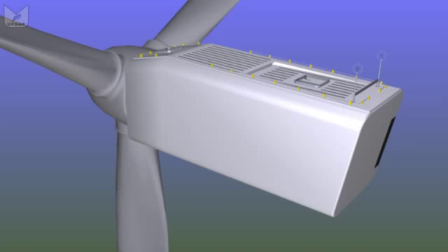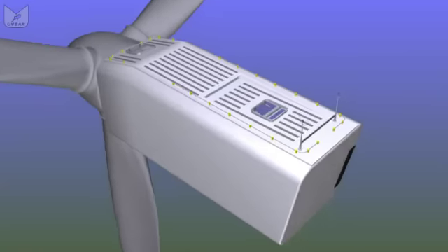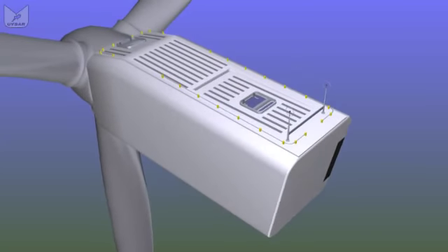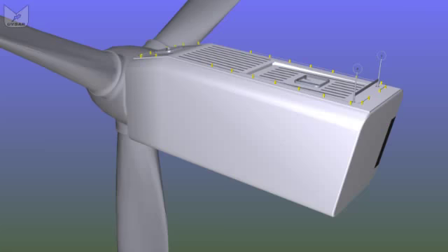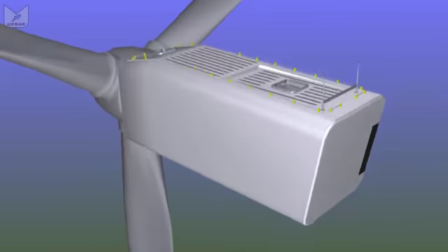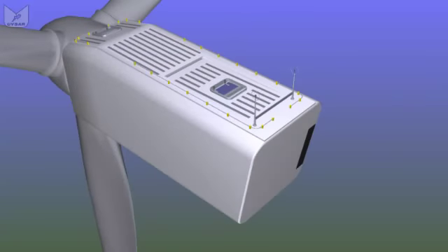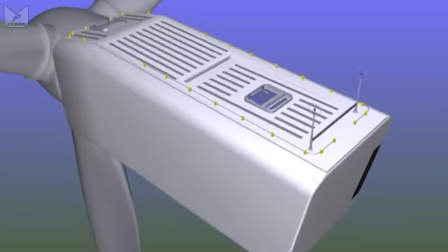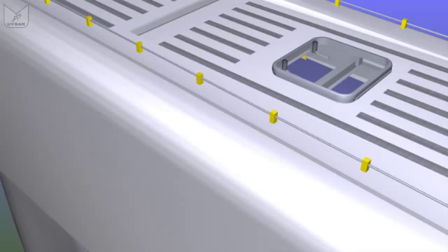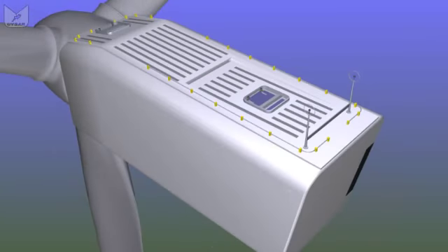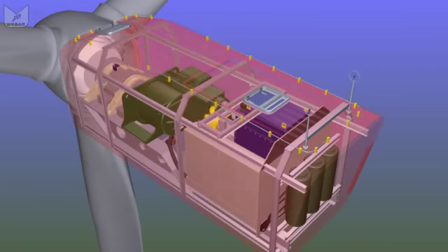And in our example, we're looking at a typical design used by a number of manufacturers where we have a nacelle that's 3 metres high, 2.5 metres wide, 7 or 8 metres long. It's a fiberglass box about the size of a site hut. As before, we have our wind sensors on the roof as far away as possible from the dirty air cast off by the blades as they spin round. This design is just a fiberglass box with a flat roof. We access the roof through a couple of skylights. Some designs are like before, a big cylinder with 2 opening doors. Some have an entire roof section which opens, rather like an old camper van.